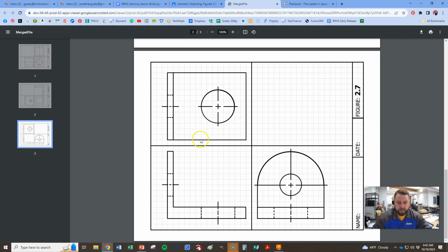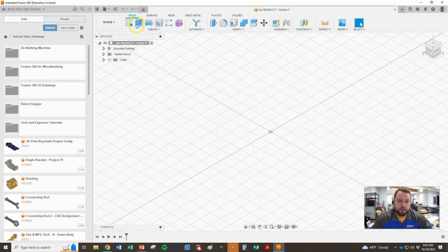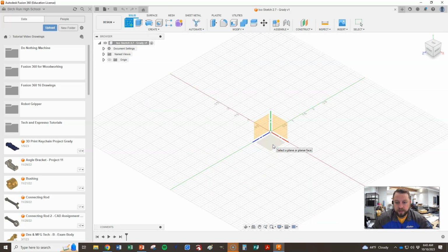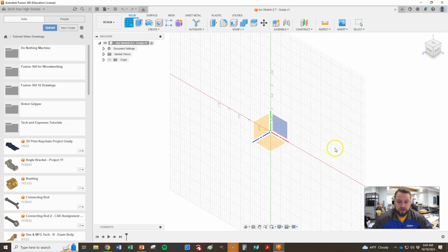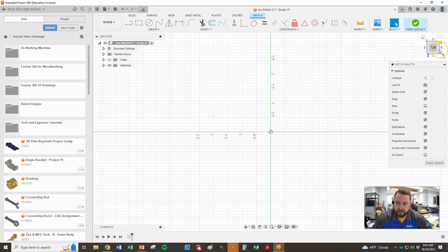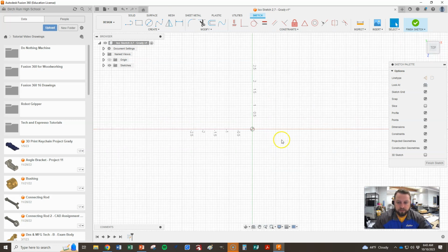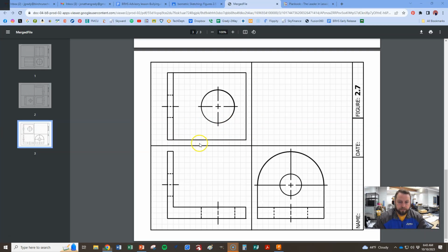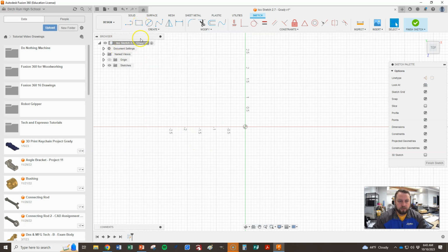All I'm going to do first is the base. I'm going to start with just the base that you see in this rectangle, and that rectangle right there is visible in the top view, right? To create my sketch, I want to have that sketch in the top view. So I click on that plane right there, and yours might be in a little different spot. Maybe it's back there on that corner, but basically we want to have this top view right there. When you click that, your rectangle over here should then say top, right? It confirms that I'm looking down on it. And then we're going to do 13 by 12, so I can go up here and create a rectangle. Well, let's check our settings first.